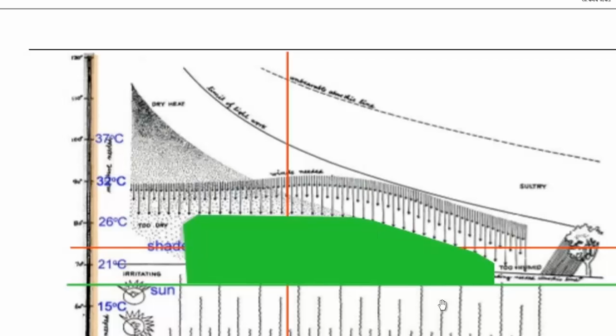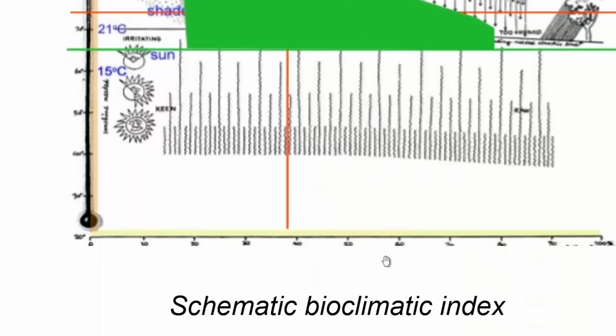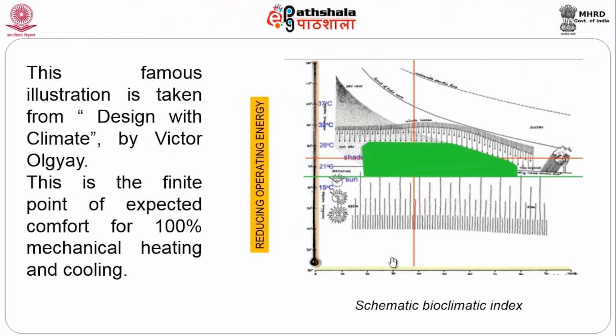And this belt is considered our comfort zone, anywhere from 21 to 26 degrees C, 28 degrees C actually, depending again on that climatic zone. As for humidity, up to 60%, up to 70% is considered a part of a comfortable humidity that we can constantly bear.